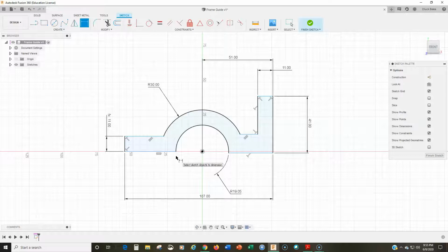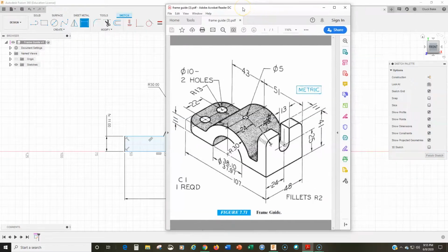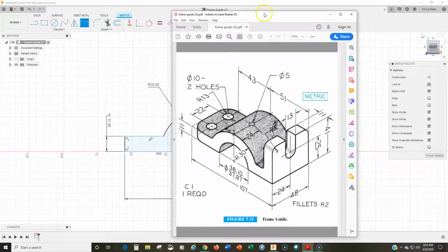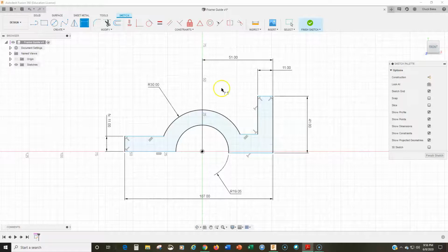The second thing is it hides dimensioning errors in the part that you're trying to replicate. So if I'm trying to draw this shape here, and the person that I'm taking this from has made a mistake in their dimensioning, if I use the dimensions that they give me, I will find that mistake, right? If they are missing a dimension, if they have too many dimensions, whatever, I will find that mistake if I use their dimensions. All right, so always use the dimensions that are given.